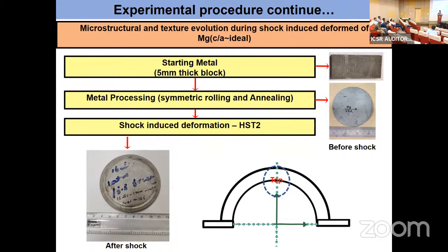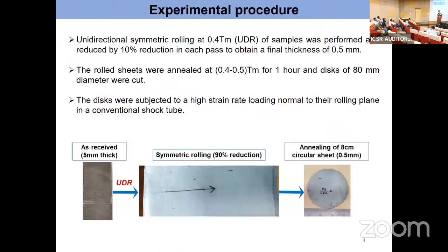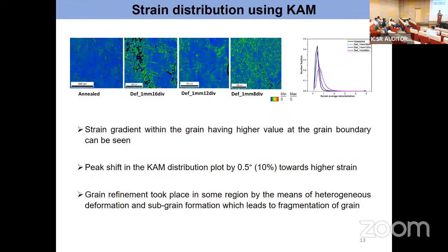Okay. And the other thing is the strain distribution plot you showed, right? How do you get the strain distribution? It comes from EBSD data, which is an SEM-based technique. So by using EBSD, I have plotted this. No, I'm not talking about the plot, I'm talking about the colored 2D contour plot. That color comes from EBSD only; it directly gives the strain value. Okay, thank you.